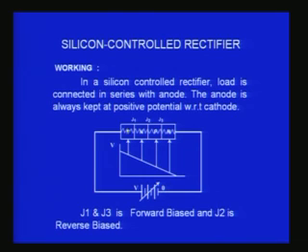So, you have a PN region, a 4 layer device, and that means it has to have 3 junctions: between P and N, J1, between N and P, J2, between P and N again J3. So J1, J2, J3 are the 3 junctions, and there are 4 layers. If I connect it to a large power supply with the plus connected to the anode and the negative connected to the cathode, and if I make it variable, what will happen to J1, J2, J3? Let us try to understand. To illustrate that, I have approximated this to a resistor here.